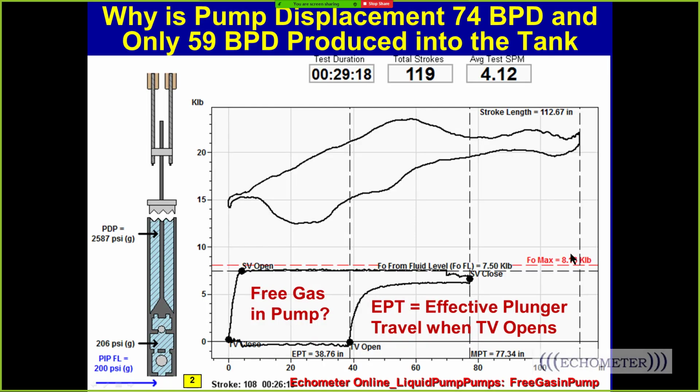So this is an actual surface card and pump card, and the pump card has incomplete pump fillage, and so this shape right here means that part of the downhole stroke of the pump, this portion of the stroke, is being lost to gas compression, and we call that gas interference. And so when we look at this shape, this means that there's gas being compressed.